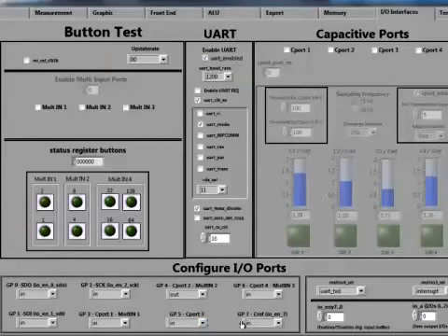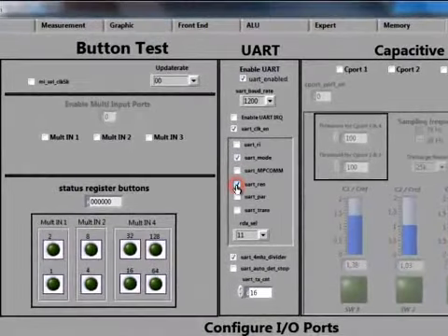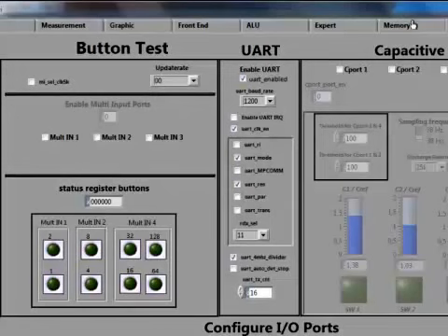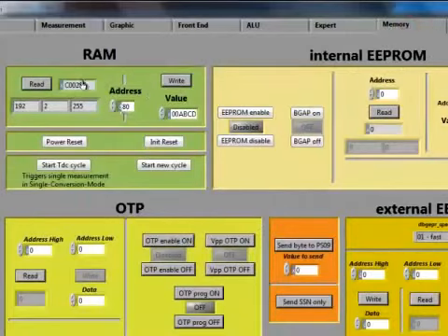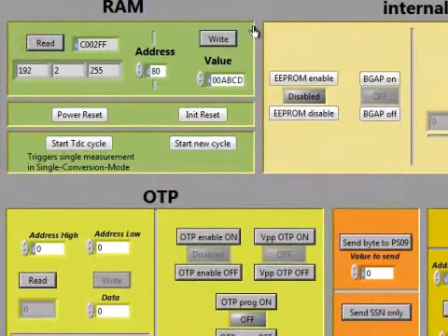Enable the digital input on GPIO 5 by setting this option here to hex 20. Finally, set the UART receive enable. When a byte is received on the GPIO 5 pin, it can be read out from RAM address 80, the lower 8 bits.